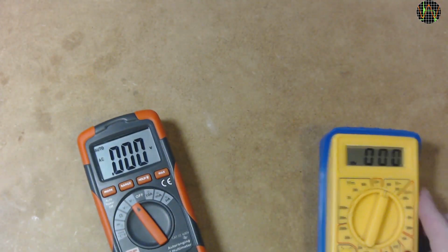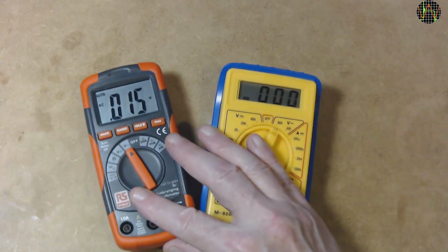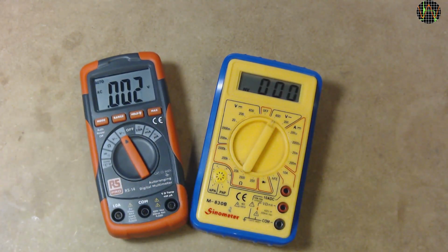First of all, many cheaper digital meters for beginners and probably all analog meters are averaging meters, so they are still around and you may in fact have one. Secondly, having one can be useful if you are servicing older electronics. In many cases, the service manuals were written when averaging meters were the norm and simply assume their use. So check values shown in the service manuals may be in fact wrong when using true RMS because the manual included the error caused by averaging in the target number. So don't throw them out just yet, but be aware of their limitations.